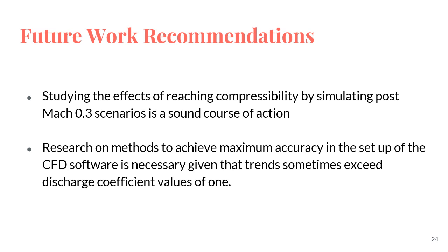We believe that studying the effects of reaching compressibility by simulating post-Mach 0.3 scenarios of air and other gases is a sound course of action, and that research on methods to achieve maximum accuracy in the setup of the CFD software is necessary, given the trends sometimes exceed the discharge coefficient values of 1. We believe that modifying the mathematical methods used by the software so the initial and boundary conditions can be more properly represented will eliminate these issues.